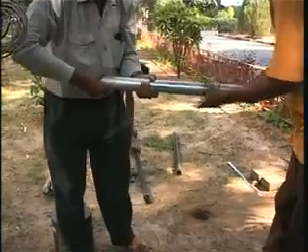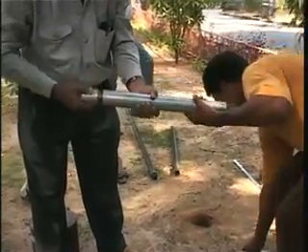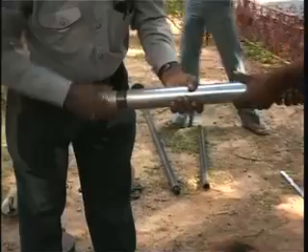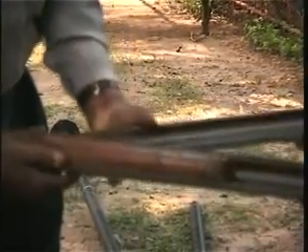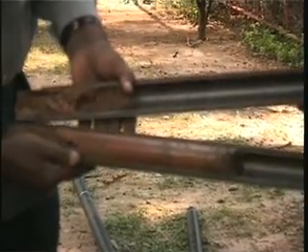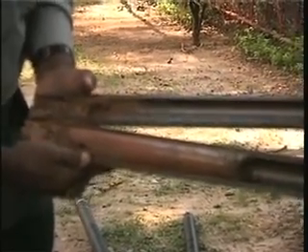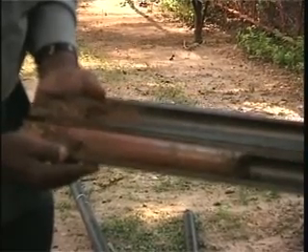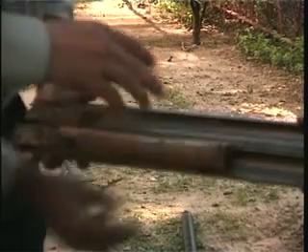Okay, now we have got the soil sample out from the ground, and we are going to disassemble the sampler, and we are going to see how the sampler looks, how the soil sample looks. So this is the soil sample that we got from down there, and this particular sample is visually identified in the field, and it is also saved. Some of these samples are also going to be saved for moisture content determination.